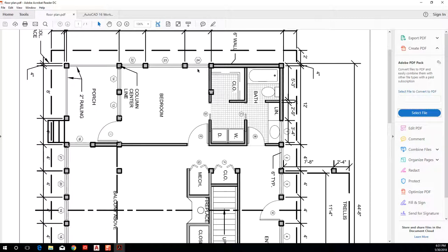So with this floor plan, we'll look at this room specifically. If we were to cut the top of this building off at a 3 to 4 foot range, the things we would see at the cut line would be the walls being cut, the windows being cut, and the doors being cut, right?